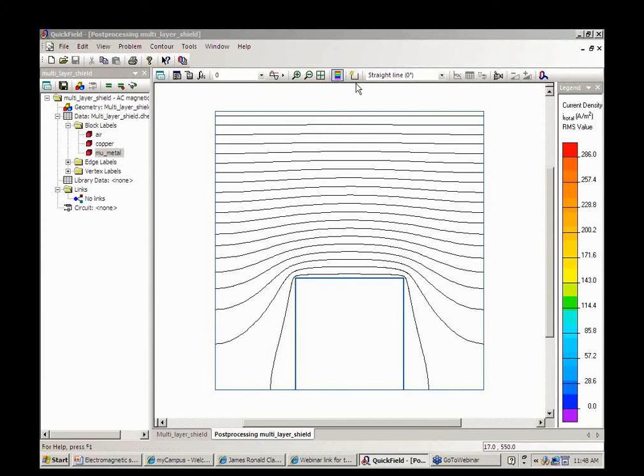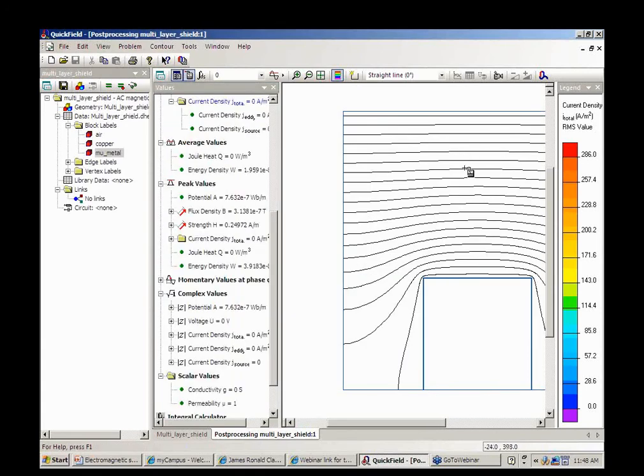Okay. And we can compare the shielding factors. Outside here, it's roughly 300 nanotesla at 50 hertz. And you can see inside here it's much, much smaller. 10 to the negative 13 Tesla. That's about 100 femtotesla, which is good enough for cardiomagnetism. If we're going to do neuromagnetic measurements, we really need to be down into the femtotesla range, which is approaching the SQUID sensitivity.